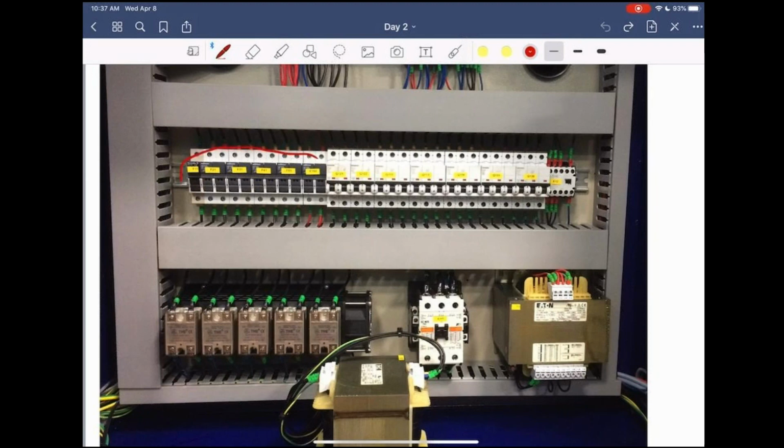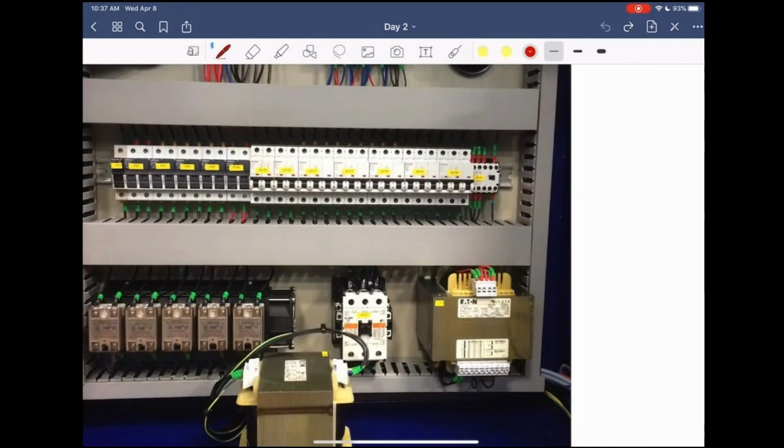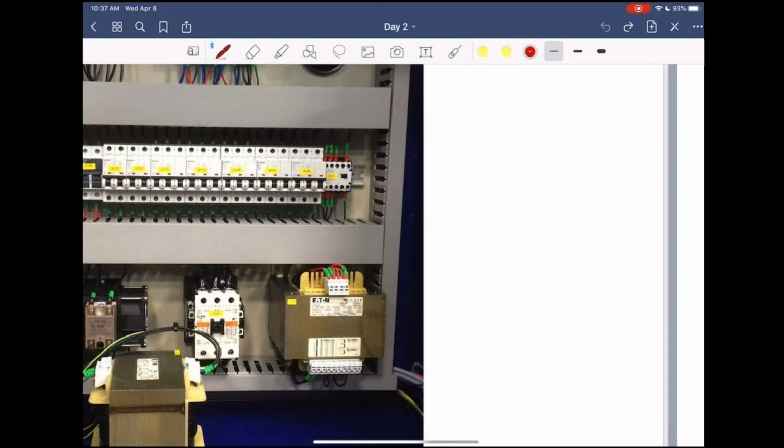These fuses here are for your different zones of your heat. Over here, you'll have your SSRs for your heaters. This is your motor on your heater contactor. So when you press the heat button, that'll engage that contactor. That's where you hear a click. We'll go on because we have more explanations. So KA1, KA2, K1, K2, K8, and K3. The first 2 are for the motors on and off. The second is for the heaters on, and the third one is for your lubrication pump.